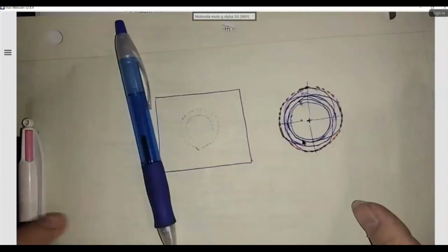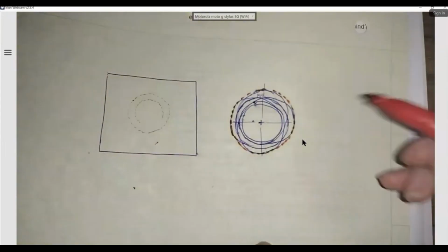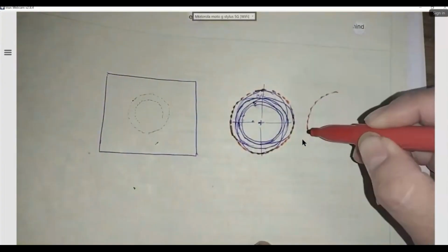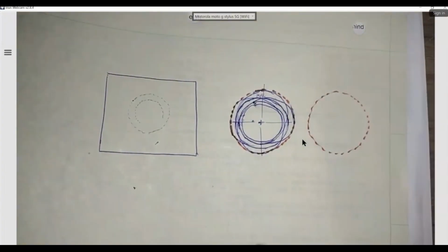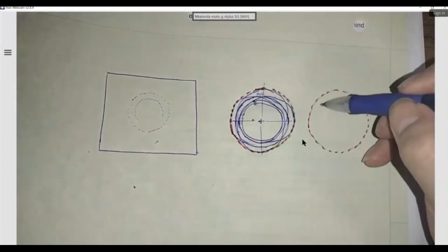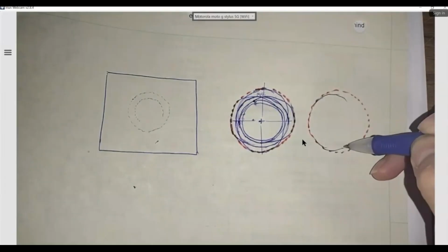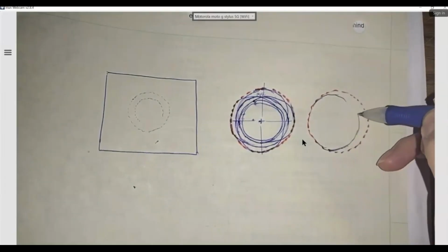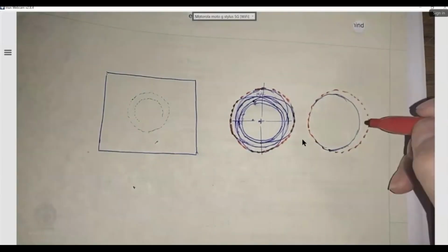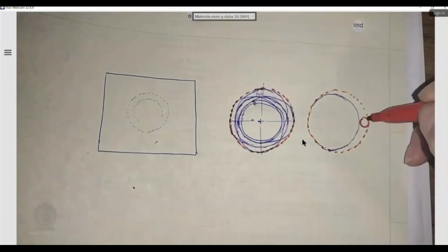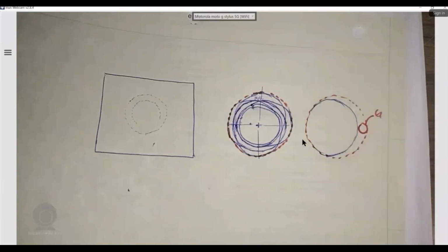If I were to grab that boundary and put it on the right side, and I were to put one of those holes and put it on one of the edges, again, we're doing MMC, right? The biggest I can get. So put it right there. And I were to measure the distance of this one. This guy is my G, which is the diameter.